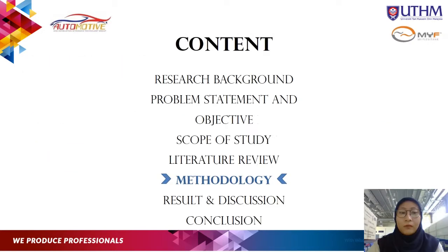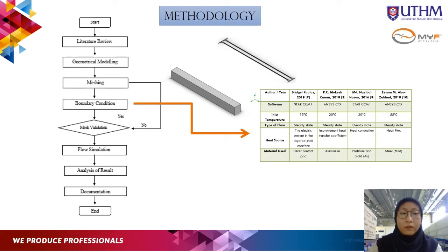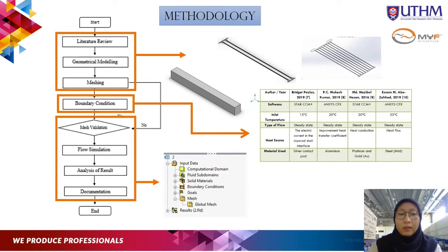Okay, next for the methodology. First we create the flow chart for the simulation. We started with the literature review, geometrical modeling, meshing, and the boundary condition. From this, we create the simplified heating pad. And next, the mesh validation, flow simulation, analysis of results, and the documentation.